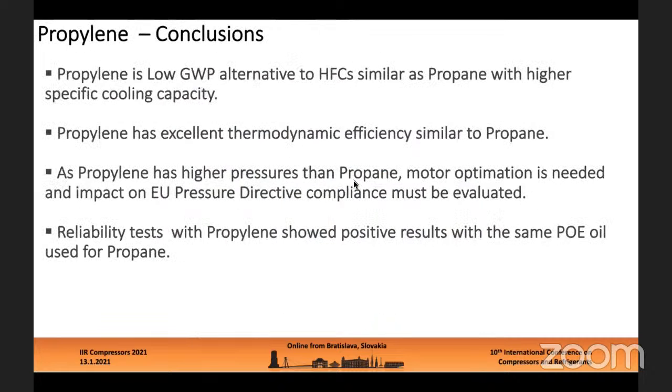So at the end of the presentation, some conclusions. Propylene can be a low GWP alternative to HFCs, similar to propane, providing higher specific cooling capacity, which can be a solution in some specific cases. Propylene has very good thermodynamic efficiency, similar to propane, so we can obtain very similar efficiencies to propane.